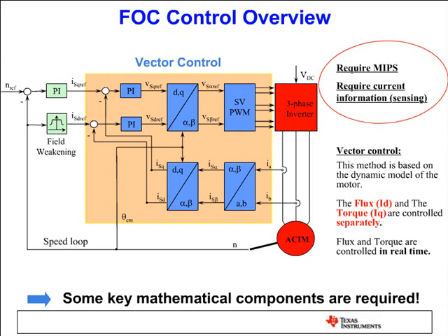And then after alpha, beta, and DQ transformation, which we call Park and Clark transformation, we decouple the current into 2 components, ID and IQ components. ID represents the flux and IQ represents the torque. So we have the chance to control flux and torque independently. And we compare these flux and torque feedback with the flux and torque references. Now I'm focusing on the orange region.